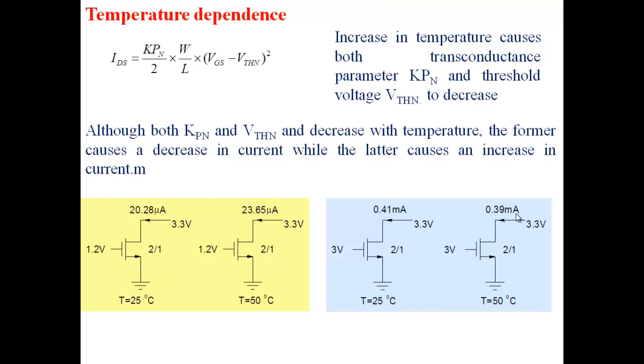So remember, if you open up 5 applications on your cell phone, your chip is going to get hot and it's not going to run very fast. And the reason for this is your MOSFET has become slower. The currents have become smaller. One simple reason. There are many other factors, but I'm saying your MOSFET has become slower. At 70 or 80 or 90 degrees, your MOSFET carries less current as compared to at lower temperatures.